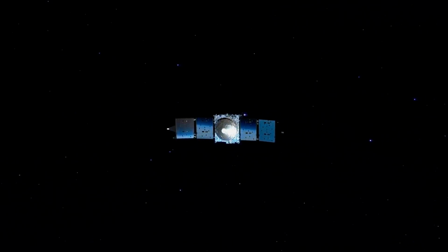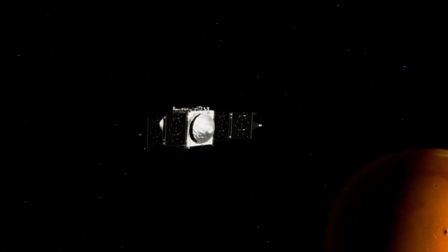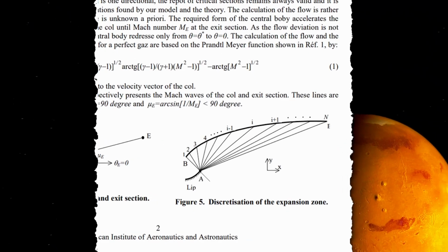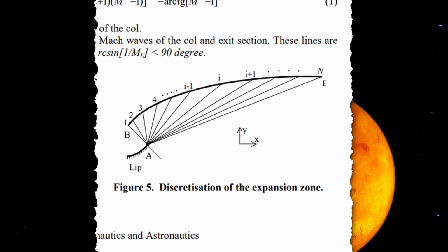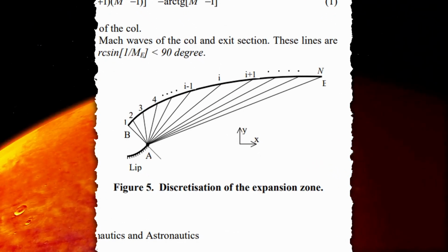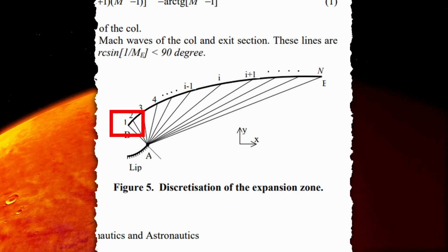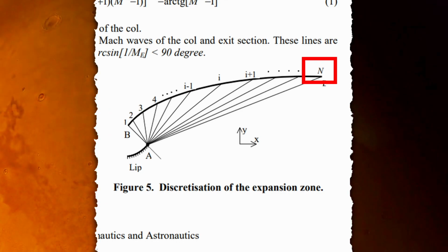At the nozzle exit, the flow is presumed to be parallel to the nozzle axis. This flow is then dispersed across multiple Mach lines, ultimately converging at the corner of the shroud. Each Mach number, between 1 and the exit Mach number, defines a specific Mach line.